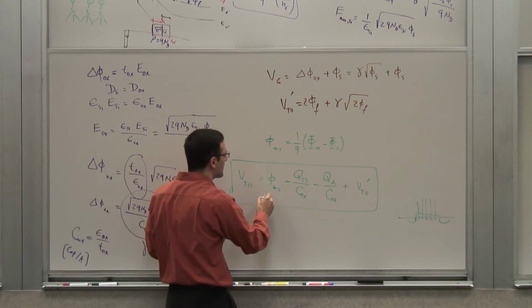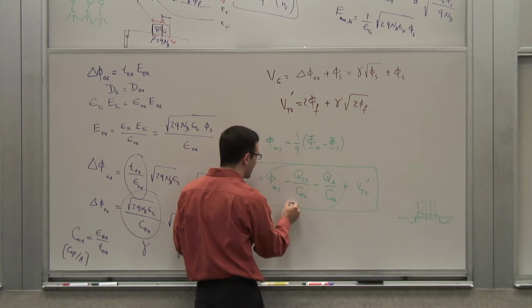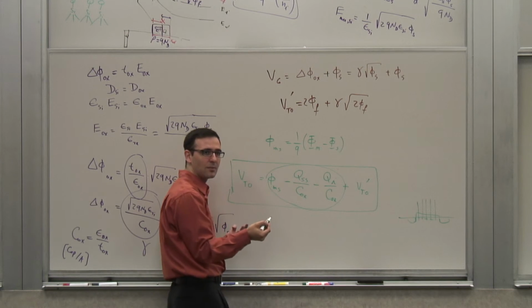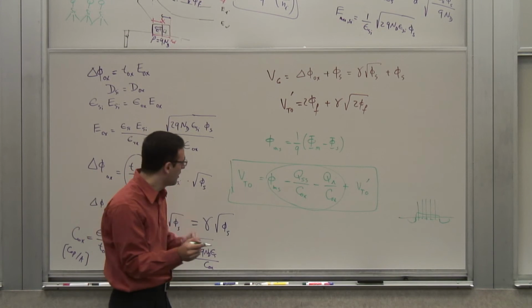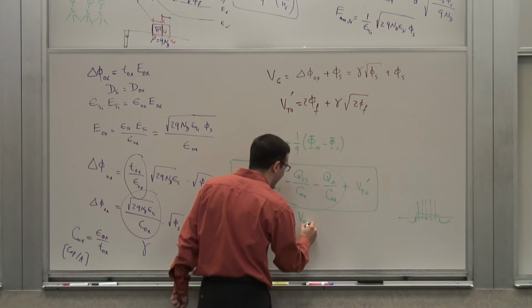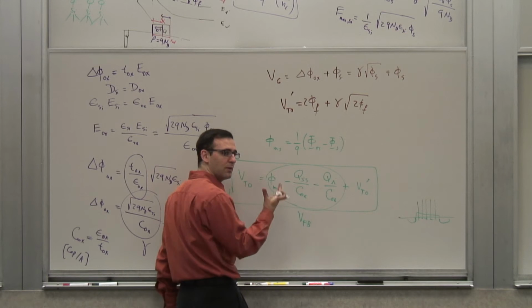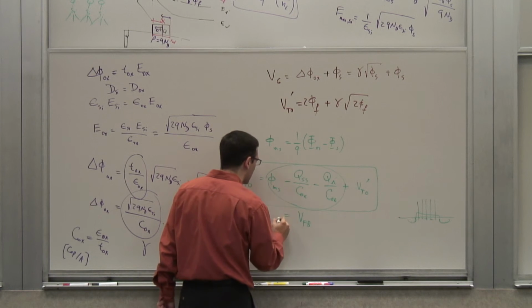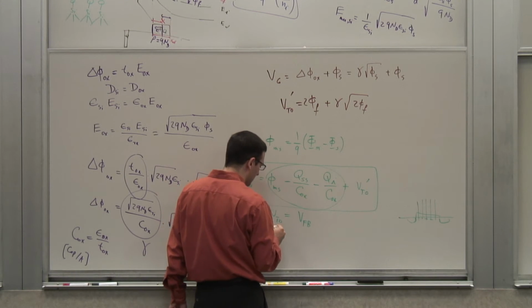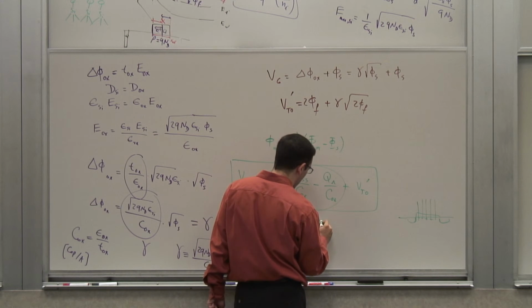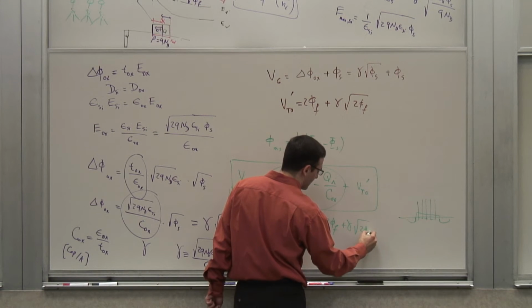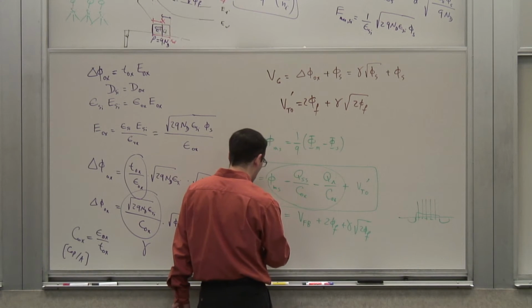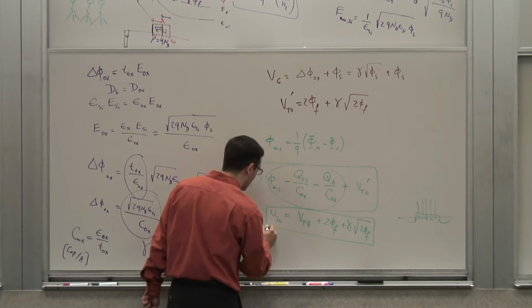Now, all of these terms take care of the second assumption. So I've taken care of the two simplifying assumptions that I made early on. The whole thing is usually called the flat band voltage. You lump all of these additional correction terms into one term, and therefore your VT0, the threshold voltage, would be the flat band voltage plus 2 phi plus gamma square root of 2 phi. And this is your threshold voltage.